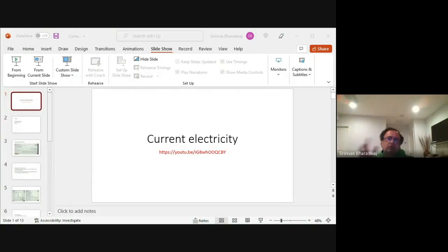If you have only one loop, it is very, very easy, right? You go once around the loop and you should get zero because of Kirchhoff's voltage law. So in this case, let me go once around this loop. This is 2 volts, this is 4 volts, right?